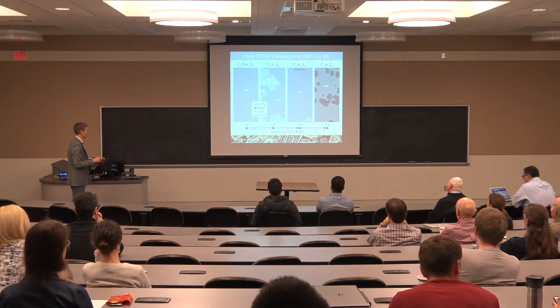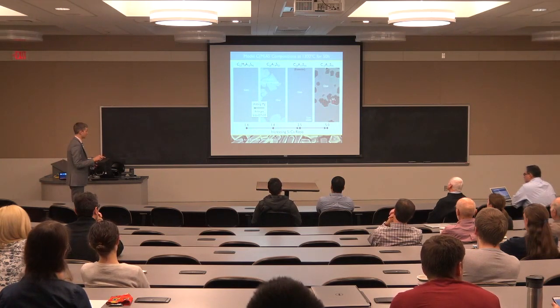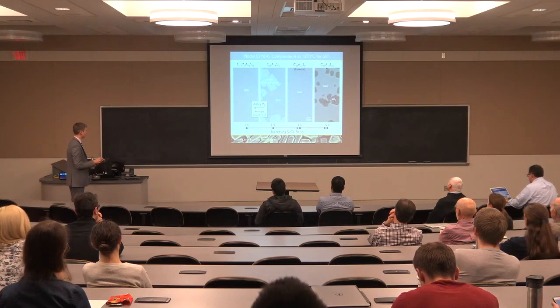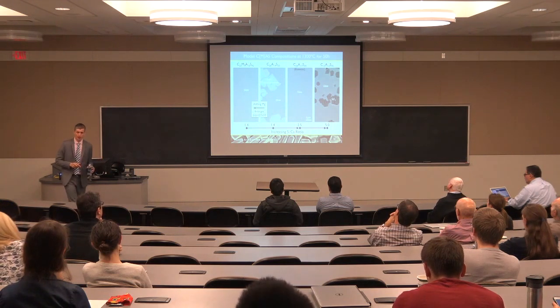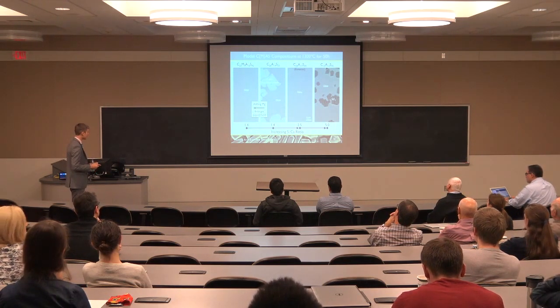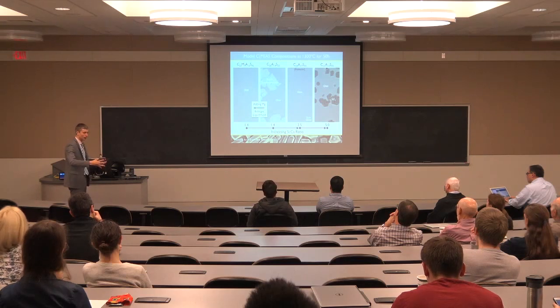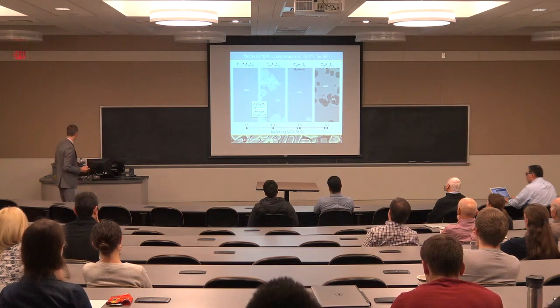And then we have these two compositions. This one is a silica-saturated system, where some silica actually precipitates out, and this represents one extreme in behavior we'd expect. This is a calcium-saturated system where some sub-calcium silicate precipitates out, and this represents another extreme in the potential behavior. The calcium-silica ratio in both of these is the same, and so we see the effect as we add magnesia that the liquid field expands. And so the more complex the deposit composition becomes, the larger the range of liquids that's relevant to study.